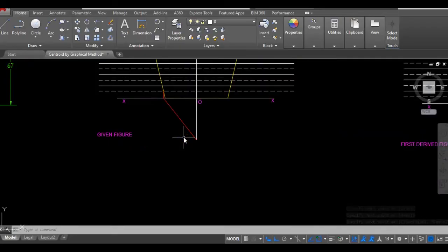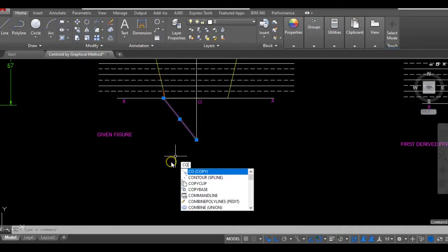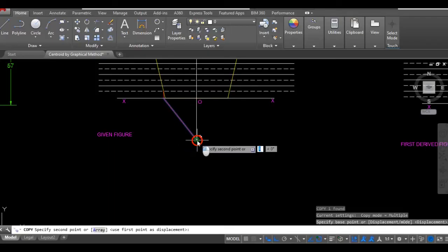Okay. So another aspect of finding the area of these shapes is getting your funicular polygon. Now, a funicular polygon is really just a link diagram that you obtain by drawing parallel lines from one point to another, or transferring parallel lines from one point to another. So what I'll be doing, I'm just going to be copying this line that I have here, using this as my base, and pasting it right here.